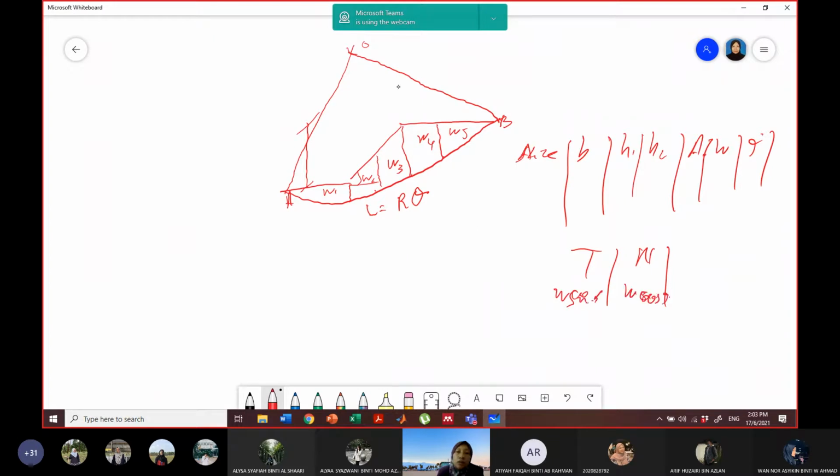So back to these calculations, I hope that every one of you understands how to get the B. B is the width of the slice. If you come from A to this point, that is the B here. And then H, because we assume that the calculations for the slip mass here for each slice is such as a trapezoidal shape.